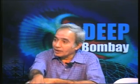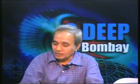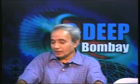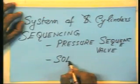See, you have gripped it. Now the next cylinder which moves the job forward must act. Wait till you grip, make sure the pressure in this cylinder is the right amount, and then only you let the next fellow go. That is what the pressure sequence valve is. You sense the pressure and then decide the next. Pressure sequence valve decides. Alternately, mostly what you have is solenoid operated valves.